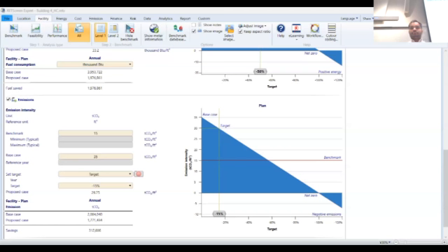your penalties are, or as they're calling it, alternative compliance payments. They are based on the metric ton of emissions, so it's not per square foot. It's per metric ton of CO2 difference between the target and how much you're emitting. So let's say you're emitting 2 kilograms of CO2 per square foot, and the standard requires 1.5. You'll be penalized for the difference, which is 0.5. And they have certain penalties. I think for Maryland, it starts with $230 per ton. So you also need to convert the units and see what it looks like.